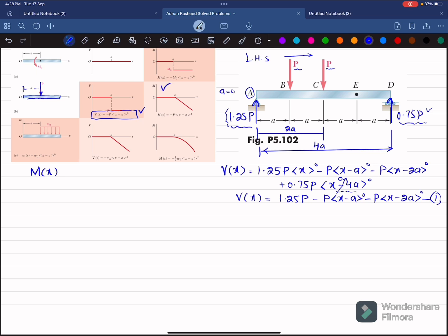So starting for this first point, our load of 1.25 P is downward here, so this is negative. For the upward load it will be positive. So plus 1.25 times P into x minus a, where a is again 0 for this 1.25 P load, so power 1.